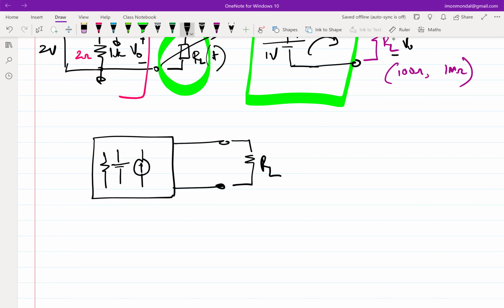So let's say I take a capacitor which is charged to, let's say, 1 volt. It's open circuited. Will the voltage remain constant? Yes. So is this a voltage source? No. Why not? Discharge. Where will it discharge? The moment I connect anything, the moment I draw charges out, the moment I load the circuit, it is going to discharge. Or in other words, I can say that voltage will not remain constant.